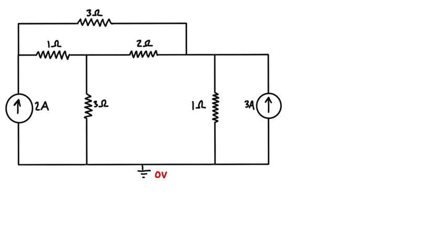It helps to pick one that has the most possible branches connected to it, and it also often helps to connect power sources to it. It doesn't give us such an advantage here with the current sources, but definitely when the voltage sources are here, you always want to connect it to a voltage source. But that's not what's going on in this problem, but we're just going to go with this one anyways because it does have 4 branches.